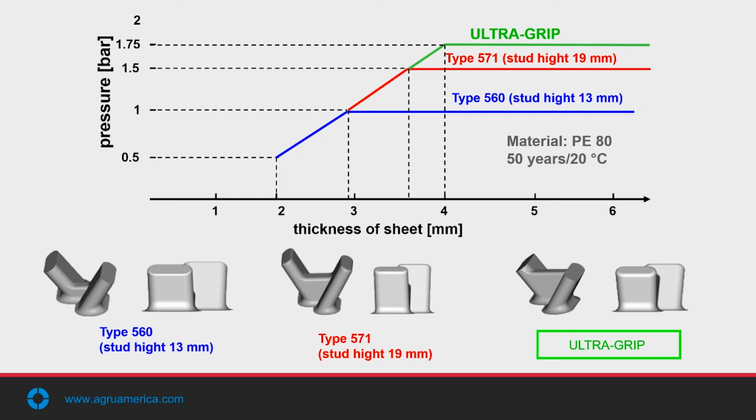We get a little higher back pressure resistance, but ultimately the Ultra-Grip system is where we get our highest back pressure resistance. All of the material made here in Georgetown, South Carolina, on a relatively new machine, is made with the Ultra-Grip anchor system. You can see that the bridge between the forks of the anchors has been raised, and in the opposite direction, the anchors have been flared out slightly. This is what gives us that additional pull-out and back pressure resistant strength.